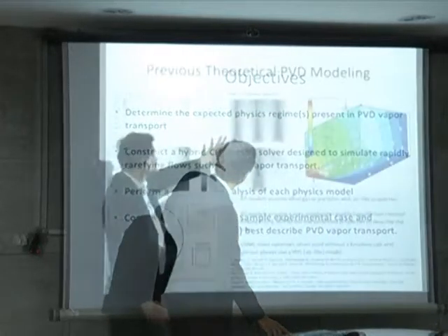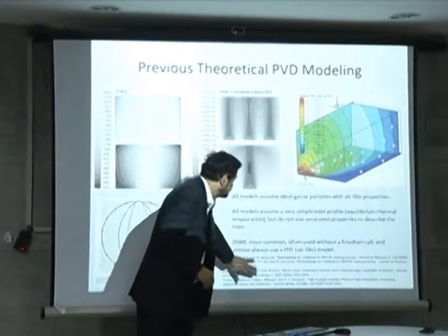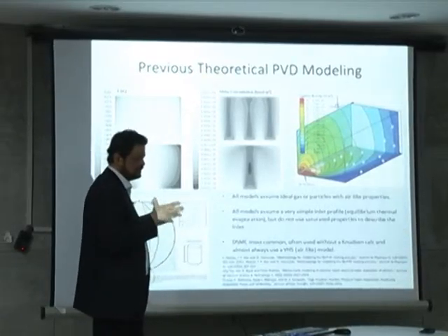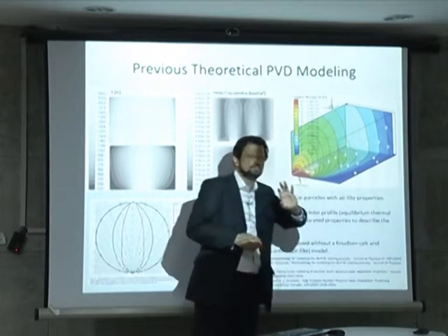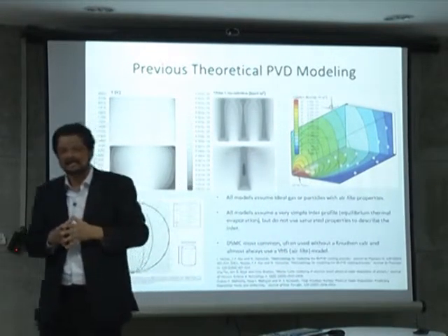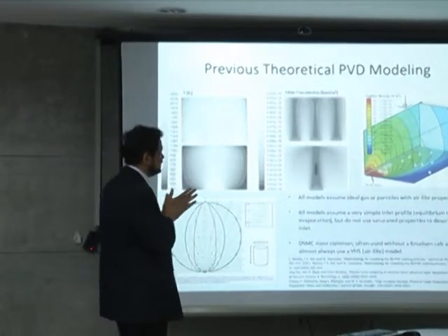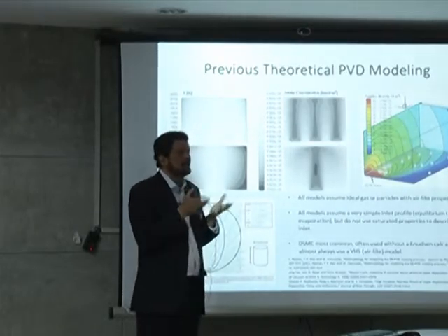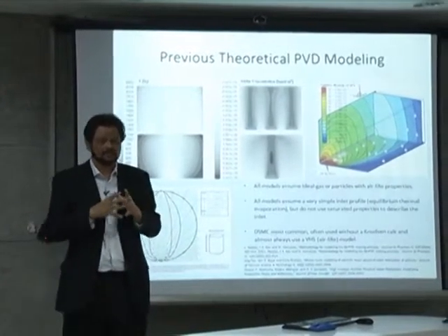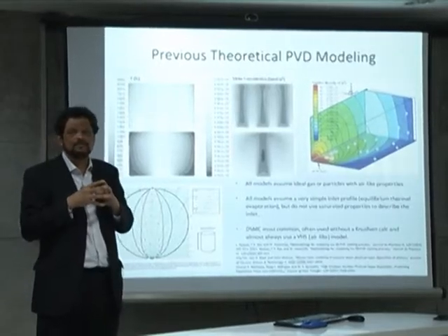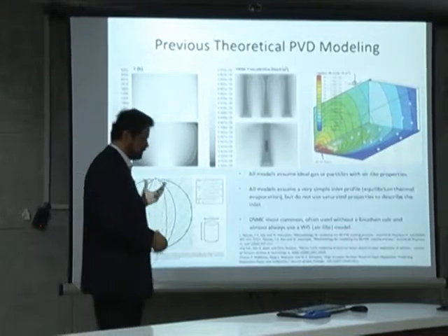And then you go with a CFD model for the whole chamber, and there are all kinds of references. This is very small type, but if somebody is really interested, we can show that. But this is a computational fluid mechanics model. You can do whichever you want. You can use packages like ANSYS or OpenFOAM, or there are many packages. But what you soon find out is that for a region this complicated, no ready-made package will do the job. One has to write different parts of it which are applicable for this.